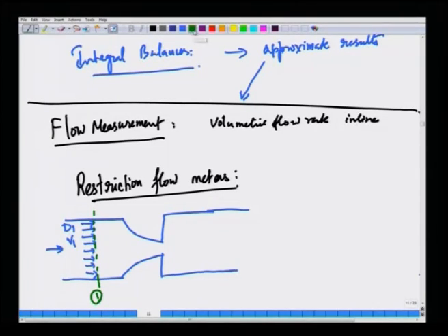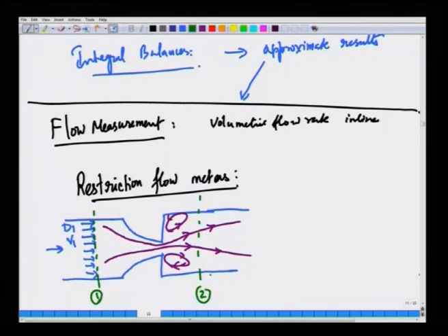The way fluid is going to flow is the following. It is going to flow like this. I am typically drawing, it is going to expand slowly, and there will be recirculating zones. Now, we can put the control surface, the station 2, somewhere here, where the fluid velocity is uniform in this direction, and it is flowing through. Let me also draw the streamline that separates, in red.